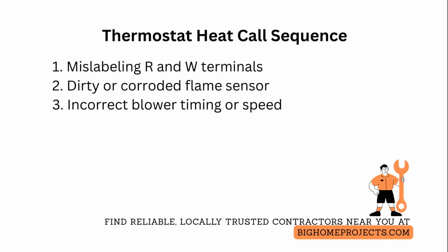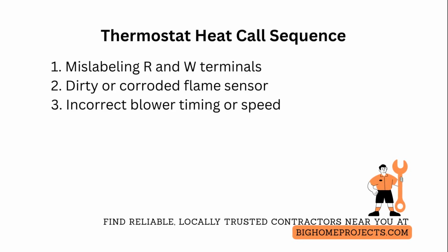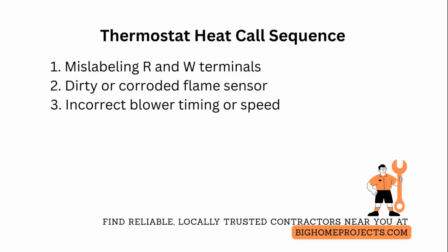Another frequent issue is a dirty or corroded flame sensor causing ignition failures and repeated lockouts. Clean the rod with fine abrasive, reinstall with correct orientation, and verify microamps of flame signal per manufacturer specs.